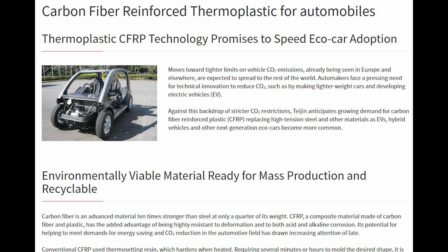Yeah, I haven't heard anything about exactly what you're describing. The closest thing I've heard of is thermoplastic films that you can have between the different layers of UD layers. What you're trying to gain with this is better impact resistance, meaning that after a high energy impact that deforms or destroys locally the fibers, you will still have a generally high strength left.